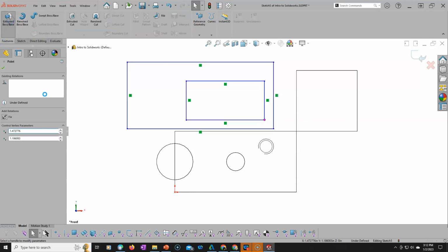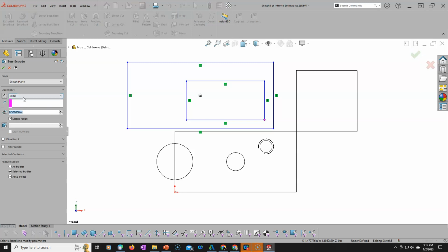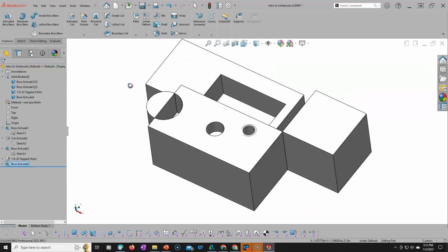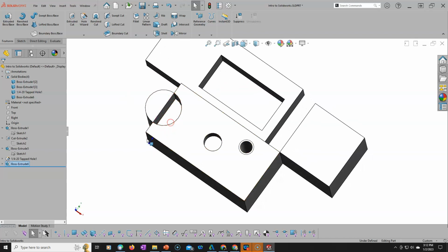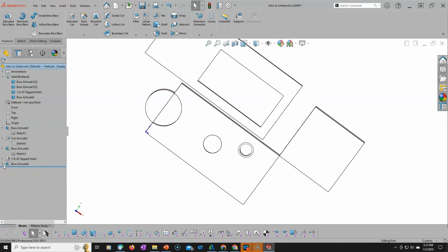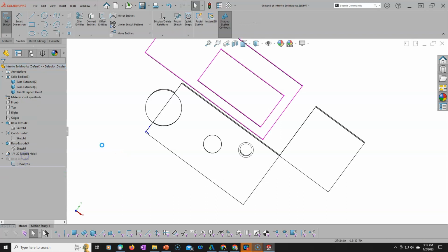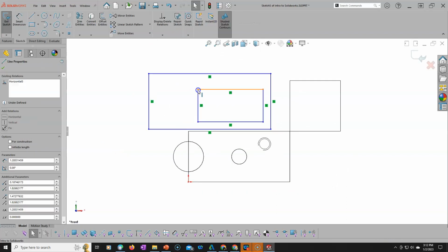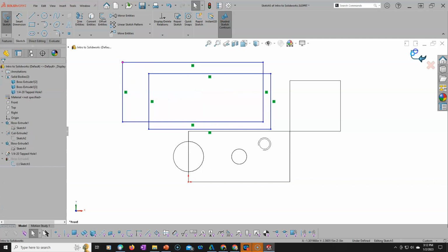As an example, if I pull that out, we can stay with the half inch, and not really look to merge the result. That's another advantage of the solid bodies, that we can turn off the merge result. So we have that piece, and just enough of a gap, and go back and edit that sketch, and drag this way, and accept.